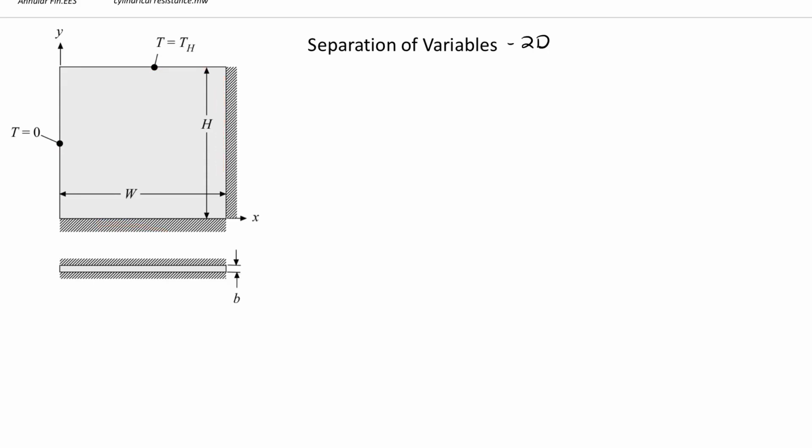So looking at this, you can see there's no way that this could be a 1D problem. Like there's no approximate solution where 1D is appropriate. You definitely have heat flowing in both X and Y because you're holding left-hand side and top at 2 different temperatures. So heat kind of has to go from the top surface down through the whole thing to the left-hand side. Okay. The other thing to point out is, we're assuming that it's insulated on the top and bottom, so it's actually not a 3D problem. Okay, so we have this problem we're going to try to solve is actually 2D.